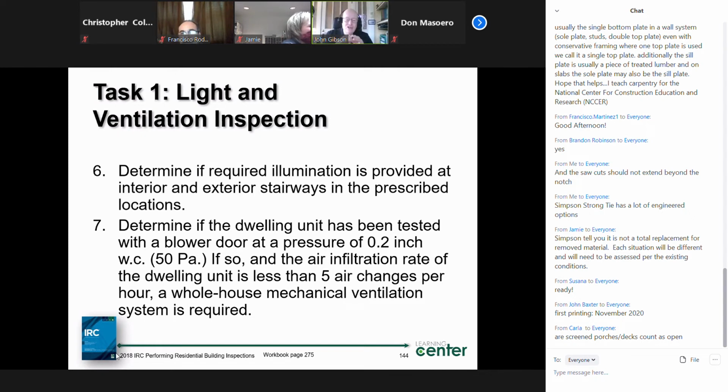Now, a whole house mechanical ventilation system basically looks at the square footage of the structure, and it's going to make determinations about the CFMs I need to get air movement through this house. So I've got to have an intake for outside air, and I've got to have a way to exhaust it. Now, we already have exhaust systems, called local exhaust systems, which are spelled out in our ventilation from the bathroom, for example, the bath exhaust fans, or you may have an exhaust fan in the kitchen over top of the hood system. So I can use those for how I'm getting the air out, but what I need to add is some mechanism to bring air into the house and structure. Now, your air intake into your mechanical ventilation system, if you have one, like a forced air, can be used for that intake function. But we're looking at this relationship that comes in.